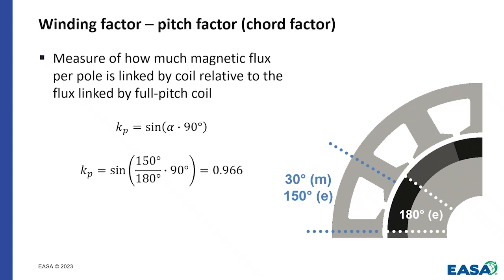In our typical or conventional induction machines that we work on every day, that number is usually 0.9 or well above that, with the only exception being 2 poles. And the only reason for that is they just become impossible to wind if we get too high on a lap winding. But it's not usually out of some desire. So we want that number to be pretty high.